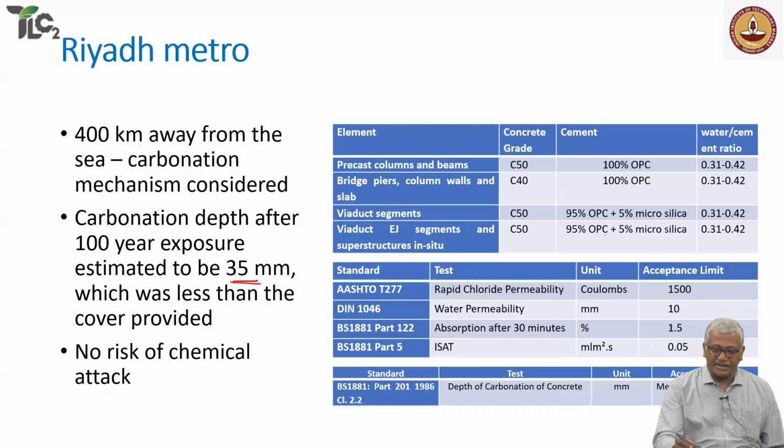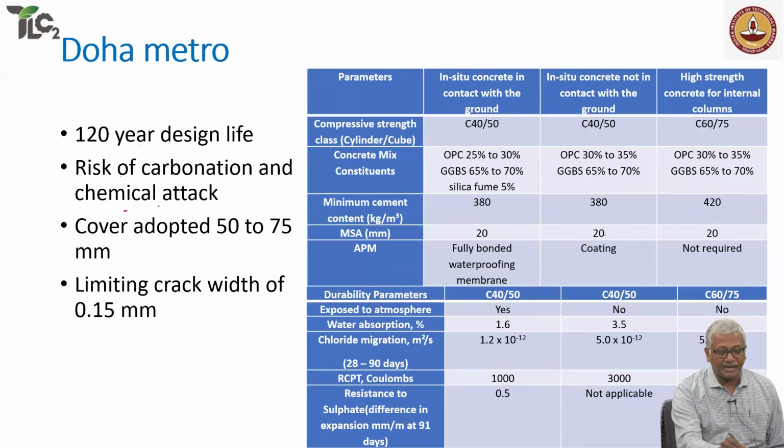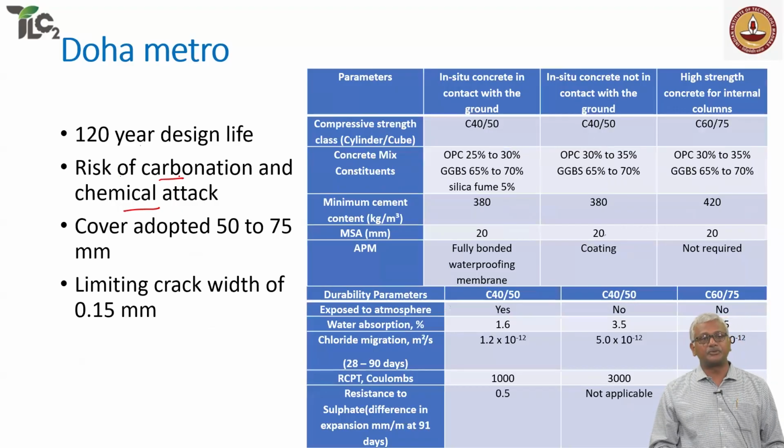Okay, and they also had several tests that were specified for assessment of durability in the concrete. And they also did a carbonation depth measurement on the concrete directly also. In the Doha Metro, they had established that there was a risk of chemical attack in addition to carbonation. So they had to design the substructure, that is a foundation, against chemical attack. So this is in situ concrete in contact with the ground.